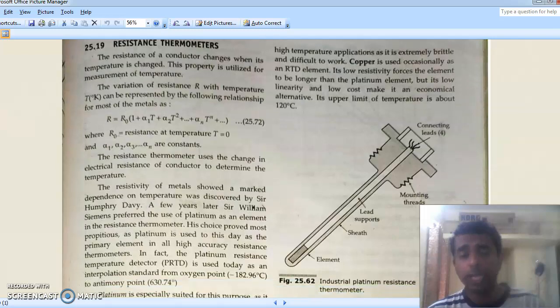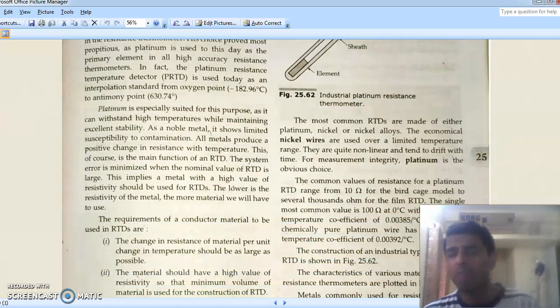And one more thing is that all these materials, whether thermocouple, thermistors or RTD, can come in various shapes like disc type, bead type, or glass coated. And many industrial transducers will come inside some housings. It can be a glass housing or some other housing. So if they are housed inside such a protective layer, they are known as probes. So RTDs, thermistors, thermocouples, all are available in probes.